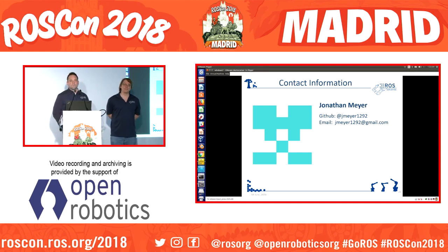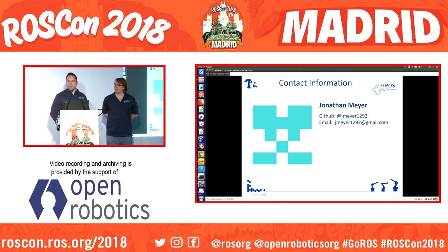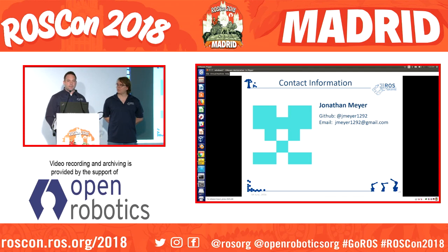Hi. Are those two planners compatible with MoveIt? And if not, would it take a lot of effort to do the integration? So we've been working very hard to get this into MoveIt. It's going to require some additional changes. We've been working with Dave Coleman, mainly because around the collision checking, it really changes a lot of it. But you get about a 5 to 10x improvement in motion planning by this alternative method. But yes, we are working to get this into MoveIt.